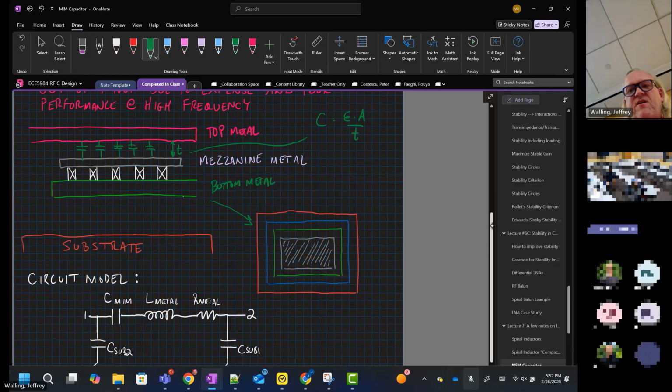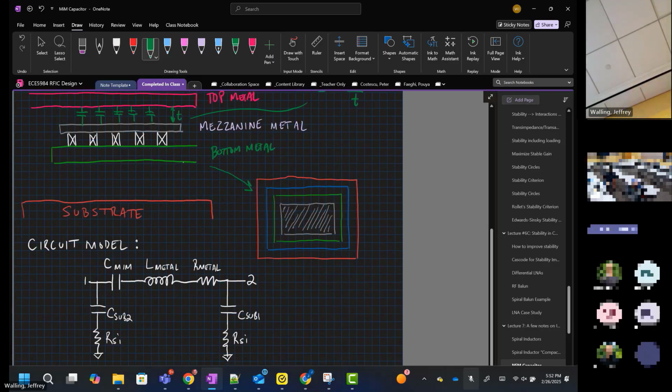All right, we have a circuit model for a capacitor. It's a little bit simpler than the inductor. In fact, we might count this and say that this is a 7-element model. Obviously, the big difference from the inductor model is we don't have that bridging element, because the capacitor itself is the bridging element. And we don't worry as much about fitting the frequency of the substrate with this particular model, like we did in the other one.